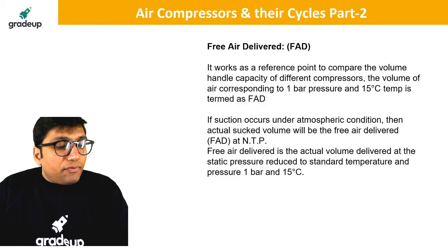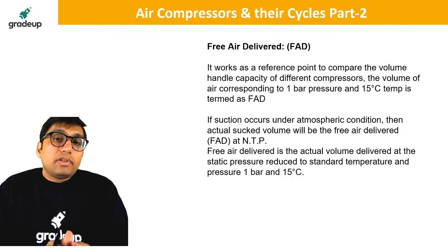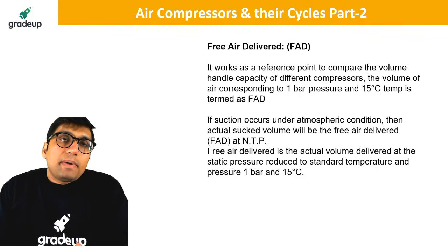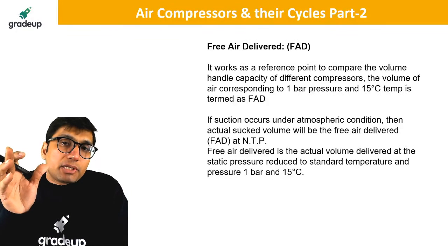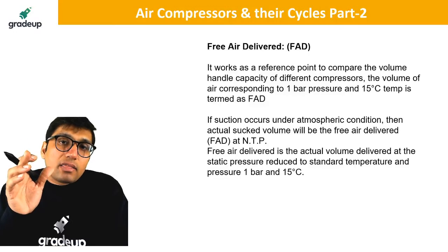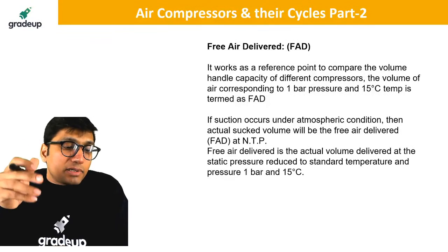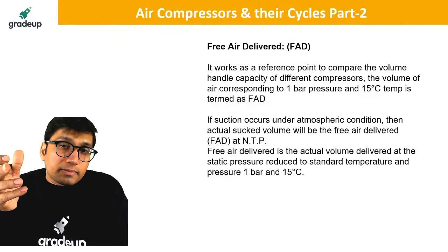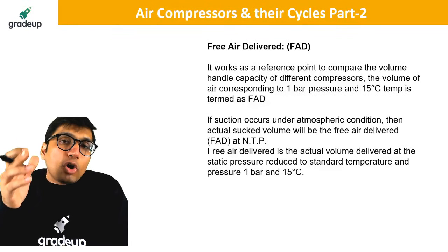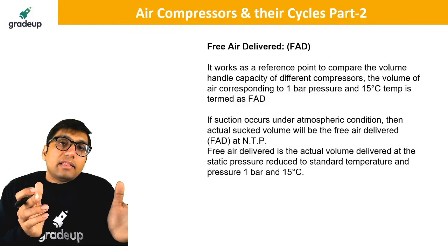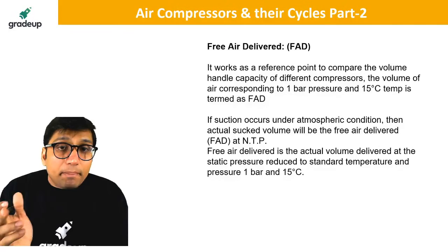Now there is a term called free air delivery. It is also a very important term with respect to compression. What is the meaning of free air delivery? Basically, as you know, a compressor will be discharging some air at high pressure, and that high pressure air will be stored inside a receiver. So what is the meaning of free air delivery? Free air delivery basically is a reference point for comparing the volume handling capacity of different compressors.